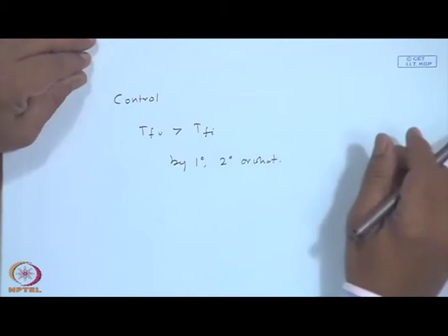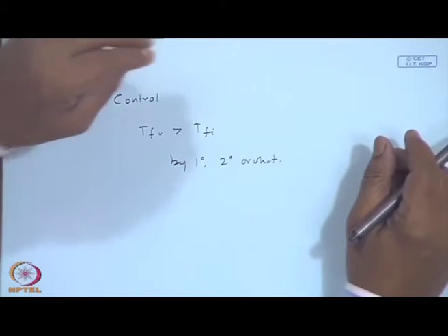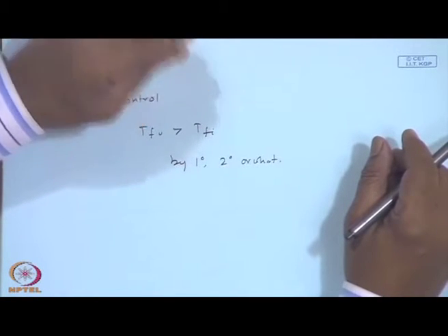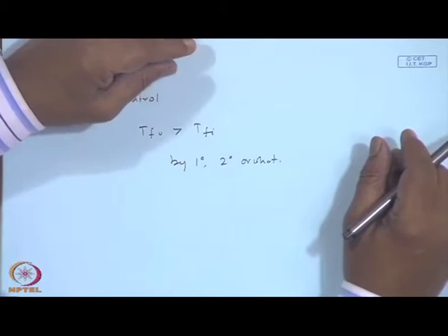So, if you put the thermostat in the control, actually you will find that it is turning the pump off or on with 5 degrees of bandwidth, compared to another control which may have a bandwidth of only 1 degree. Which one is better will depend upon again your utilization and applicability.